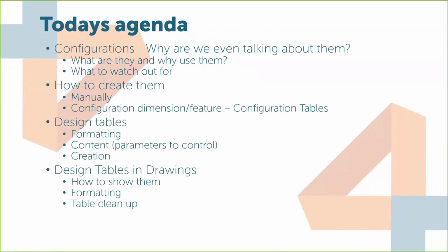Again, I'll go through hopefully a brief example of manually creating a design table in SOLIDWORKS. You can also manually create configurations, and then I'll get to design tables. But you can also create configurations using what I simply refer to as a configuration table inside of SOLIDWORKS. I'm not going to go through a live example of that. I'll just throw up a couple of screenshots to familiarize yourself with that functionality. And then we'll get to design tables, their formatting, the content, and the parameters that we can control.